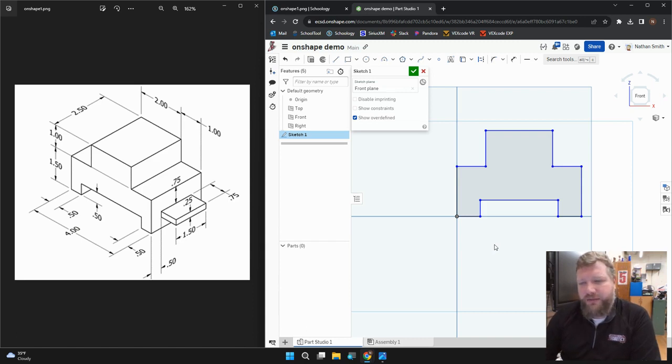So when you're designing something that's going to hook onto the Vex part, there's a lot of relationships with those squares and stuff like that you're going to want to do. Okay. So once I have some of those set up, it'll make it easier. Now I'm going to start to add dimensions. In my drawing, the dimensions are all rotated around a little bit. So dimensions going this way are going to show me width. Dimensions that are arrows going this way are going to show me height. Dimensions going kind of back at that back angle are going to show me depth measurements. So I'm going to kind of pick one and go from there.